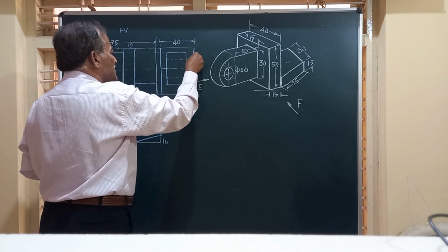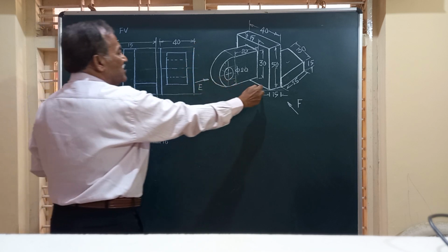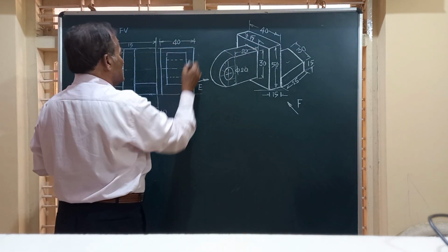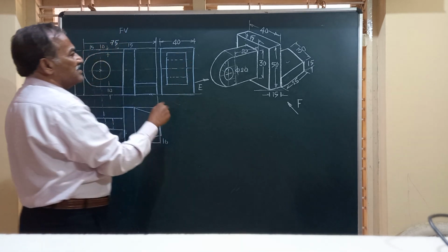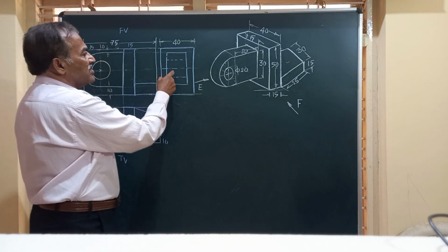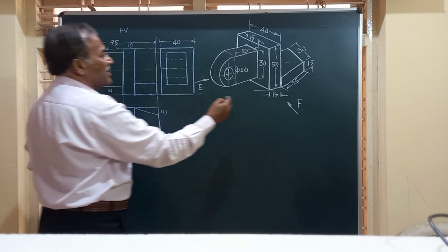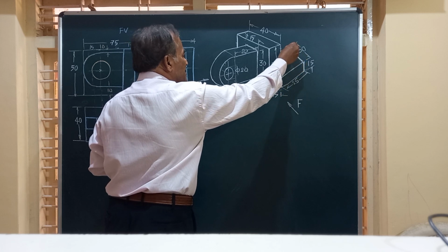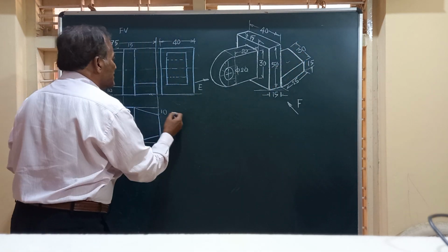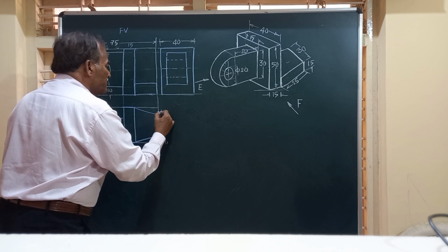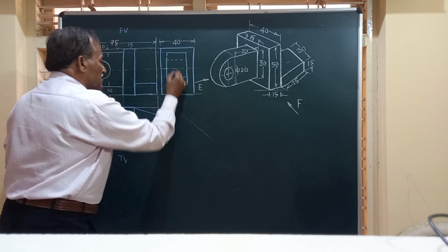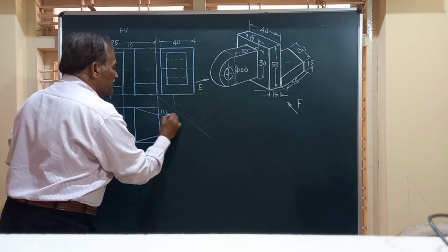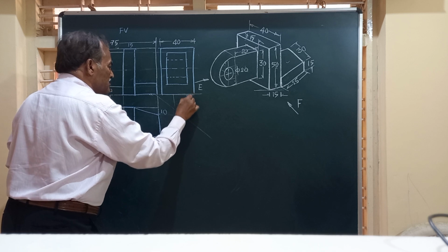This is the height equal to 50 mm, and then width equal to 40. And you know, friends, this should be symmetrical. So the hole I have drawn, friends, what else you see in the bottom, there is a thickness of 15 millimeter. This end is not visible, this end is not visible. So at the given distance, you can just project onto the end view from here, a line from here. So you get it somewhere here. One line, again one more line for this end.